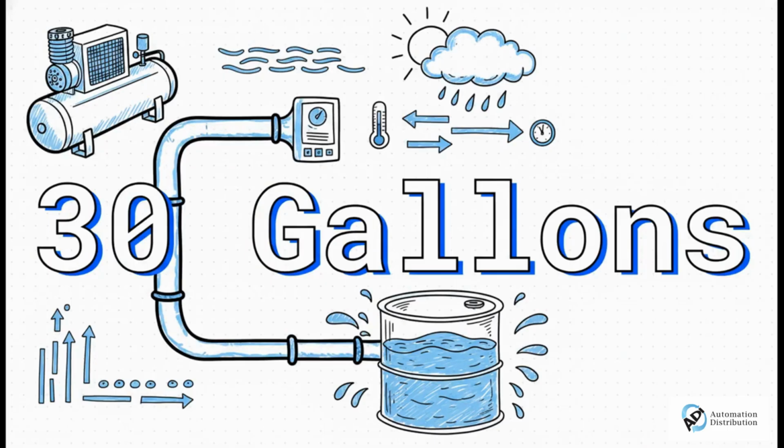To put that into perspective, this number completely blew my mind. 30 gallons. Just think about that volume for a second. If you have a standard 100 horsepower compressor operating on a typical summer day, say 86 degrees Fahrenheit with 80% relative humidity, and you're compressing that air to 100 psi, that single system is going to generate roughly 30 gallons of liquid condensate in just one 8-hour shift. 30 gallons. And again, this isn't a leak. There's nothing broken. That is just your system working exactly as physics dictates.